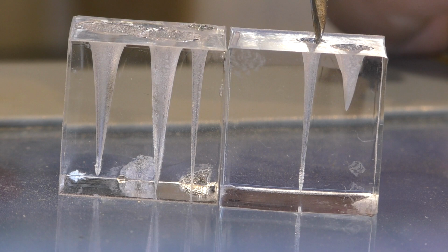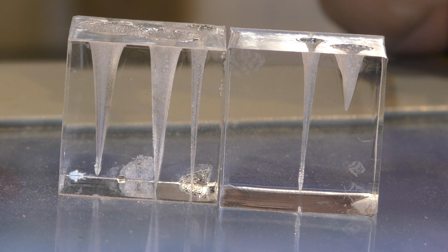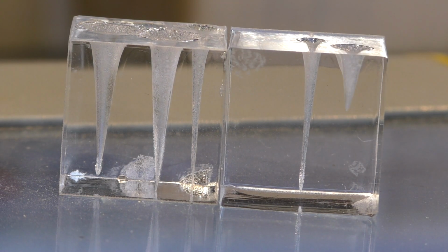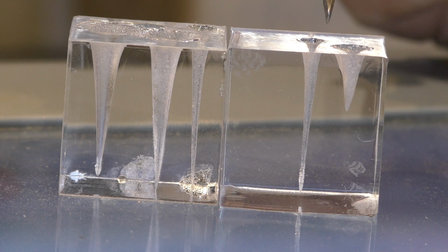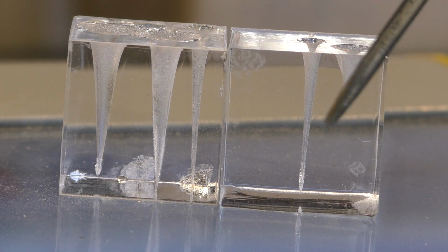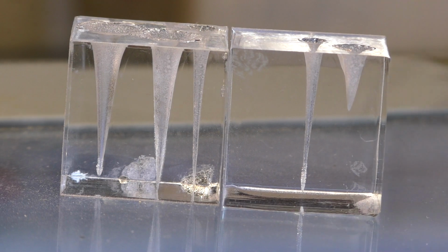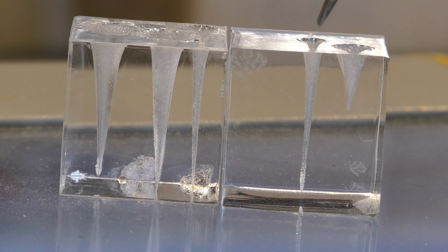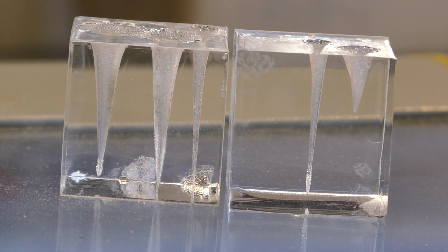And as you can see, the 30-watt tube has done just as much damage as the 70-watt tube. So in terms of intensity, which is the point that I keep making, the intensity is the thing that does damage, not power. Because of the way in which I've created the beam on the RF machine, it isn't a uniform beam. And so consequently, I can move this test from the centre of the machine, where I generated this and I've got my smallest beam, to the top corner of the machine, where the beam is a lot bigger, around about 6mm diameter here. And you can see, look, changing from 3mm to 6mm has caused this massive difference in intensity. And the different intensity has caused less damage.